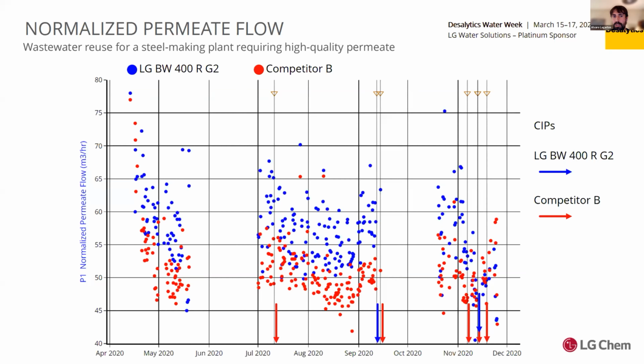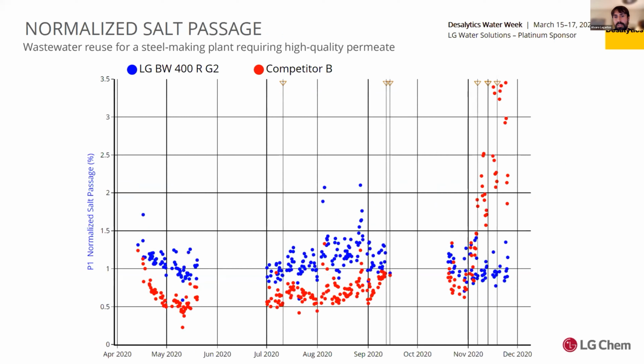Therefore, if you are able to reduce that fouling rate, then you are able to space longer the CIPs required, which at the end translates into reducing the chemical consumption, and also you are increasing the durability of your membrane. So all those little things come just from minor modification and optimization in your feed spacer.